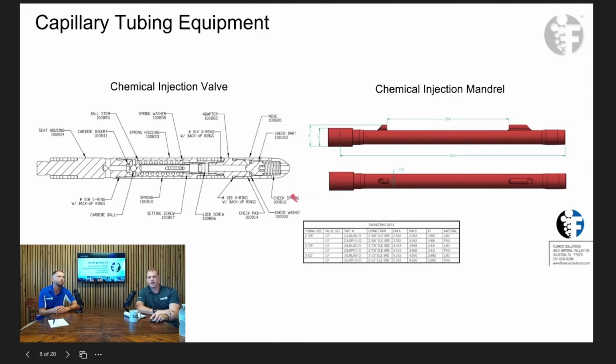Right. Which you've got to be careful with too, because you've got to check with your chemical guys, making sure they're putting the correct chemical to the string, or to the L80 lug that's there. You don't want to corrode that out, because if you corrode that out, now you're loose. Gotcha. So sometimes the chemical can actually be corrosive to the tubulars downhole? Right, we've seen that happen before. And in a case like that, you'd want to change your material, maybe go to stainless steel or a 13 chrome.